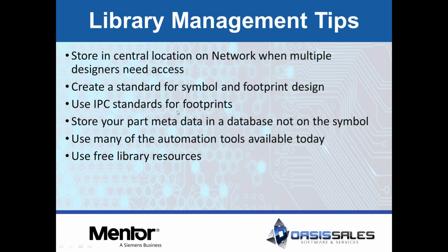Don't try and go off and make footprints where the pad geometry and stuff, you're just trying to come up with some size. You're going to find out in the long run that your assembly process isn't going to work. The IPC standards are there. Use them. Like I said, if you're a Mentor Tools customer, all of our wizards are based off of this and follow it to the T's. So take advantage of that as well.